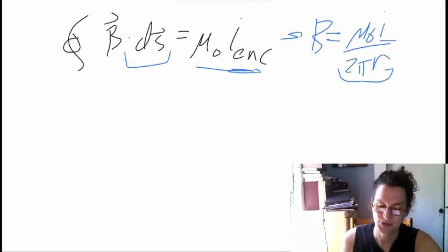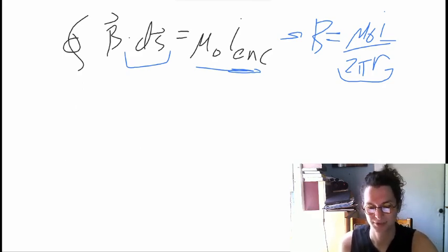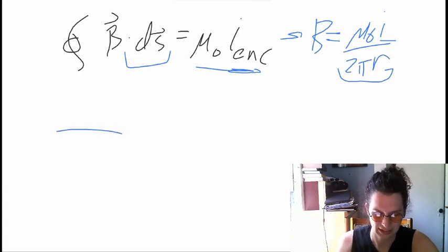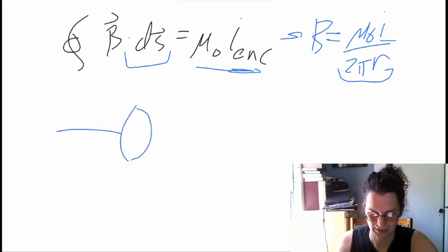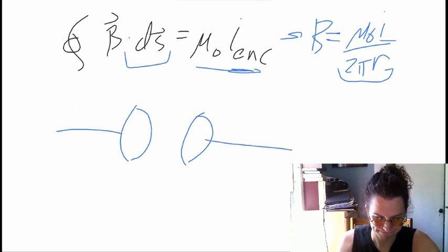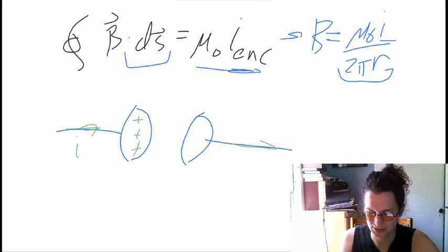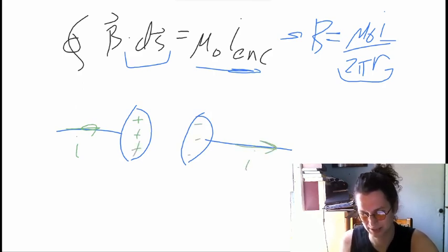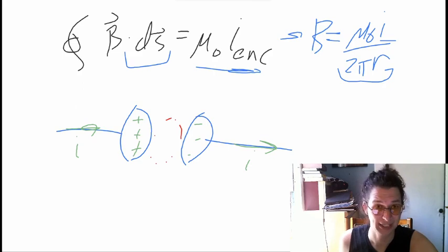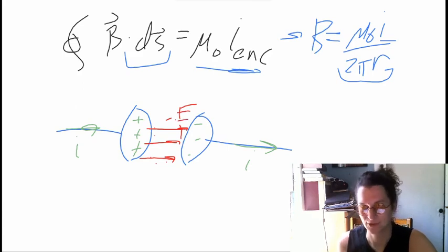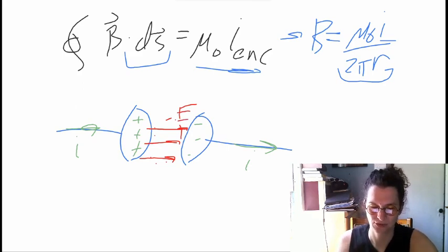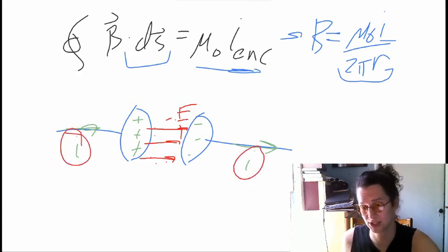The most common example of a displacement current is between the plates of a capacitor, where you have, say, a wire connected to your parallel plate capacitor and then a wire coming out. I have some current here that is building up charge on my capacitor, and that same current is over here with charge building up. In this region, no charge is allowed to flow through, right? But we do have an electric field, and that electric field can be related to something called the displacement current in that region. That displacement current will be equal to whatever the current is that's flowing through the circuit.